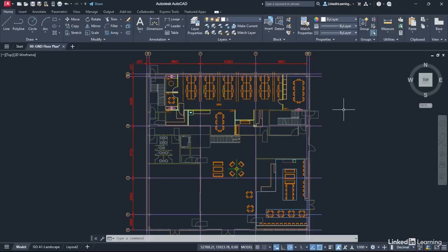So if I measure a door opening, say in this drawing, and it's 900, you know that that is millimeters in context. If it was 0.9, it would be meters. If it was, say, 36, that might be 36 inches. If it was 3, it might be 3 feet. Just to give you an idea of conversion between units. We are using metric millimeters in this particular drawing, and everything is drawn full size in the model tab.